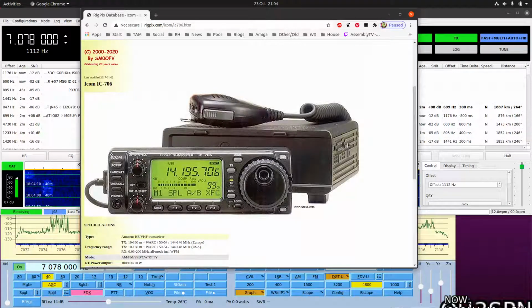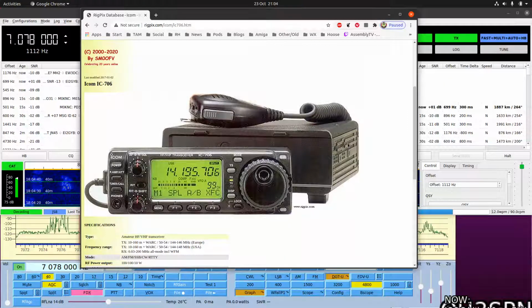And of course on the 817 the filter is in the TX side as well. So not only did it improve reception significantly, it also gave me much tighter audio on the TX side, which made it narrower, punchier, and higher signal on the receive on the remote station hearing me. So filters, traditional filters were awesome. DSP filters, at least on a modern FPGA, I just don't think they're there yet.